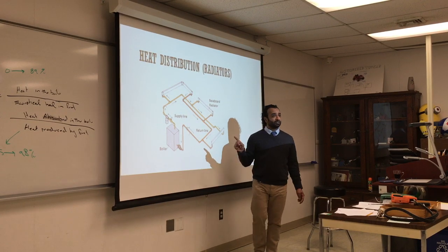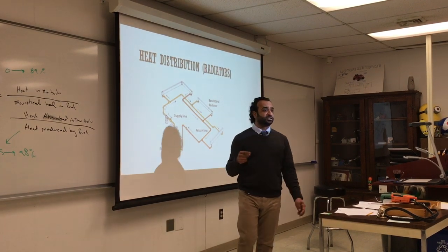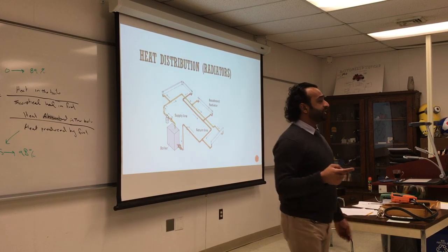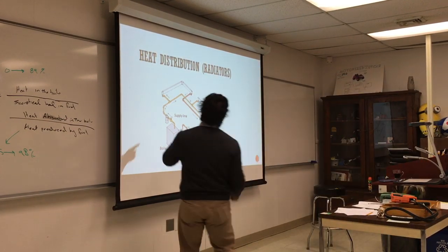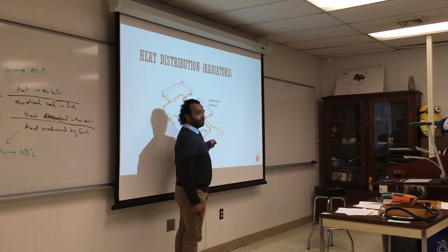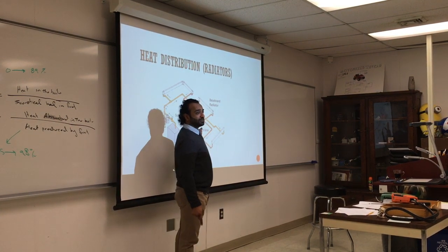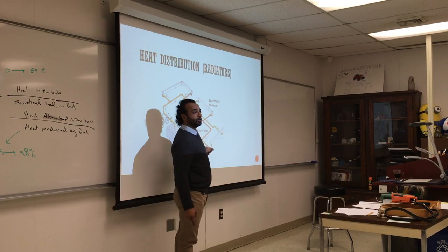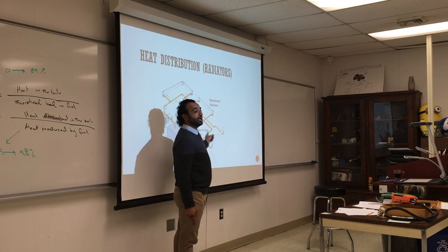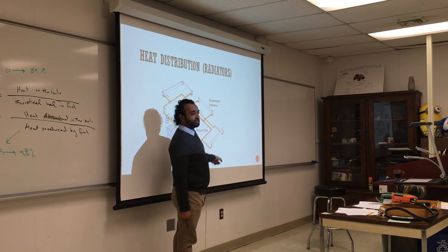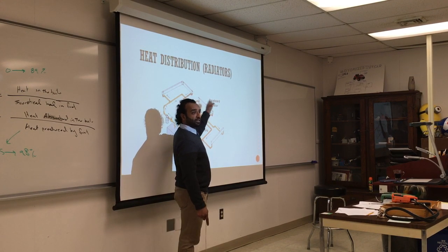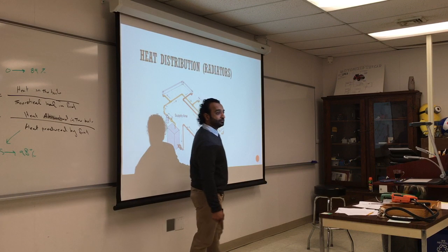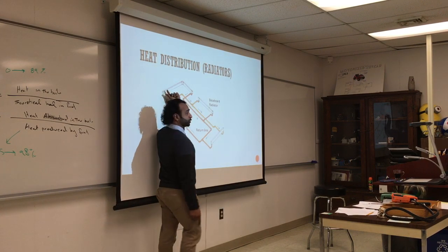So remember when we talked about resistances in series and resistances in parallel? We said everyone gets the same voltage. So the same thing, every radiator is getting the same voltage now, and the flow is the amps. The amps will distribute to each one. The resistance is different. However, everyone will get the same pressure and the same temperature. The water is coming at 180, and every radiator will get 180, because each is only taking a portion of it, not the whole thing.